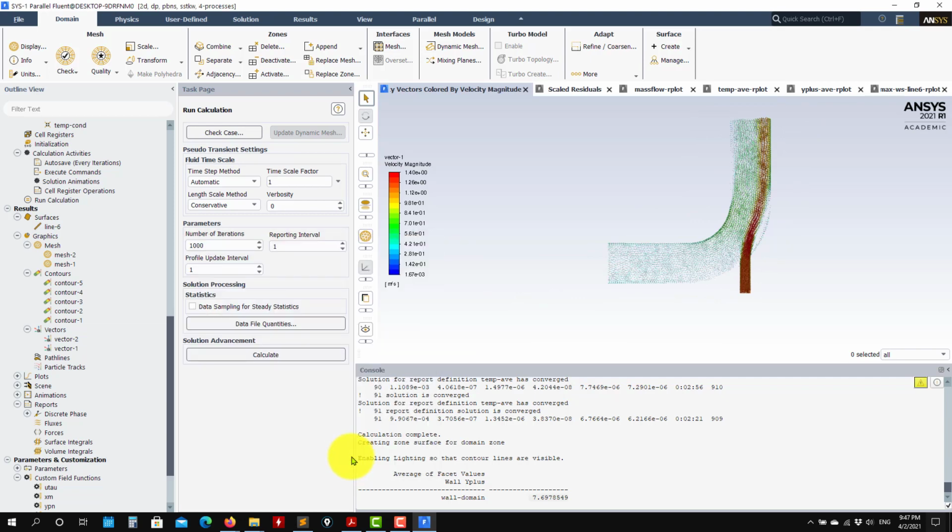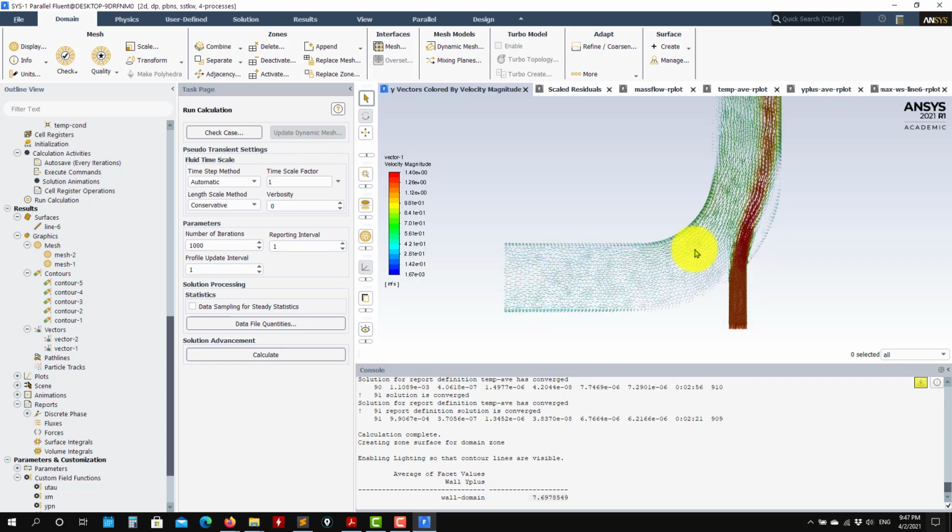It's likely laminar is the wrong solution, but it's not wrong because the laminar equations are wrong. As we have seen, the laminar equations are the exact Navier-Stokes equations, DNS. You need extremely refined meshes, and you need to go unsteady to capture the right physics. Okay, so at this point, what I want to do now is move to plots.